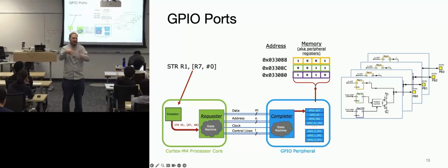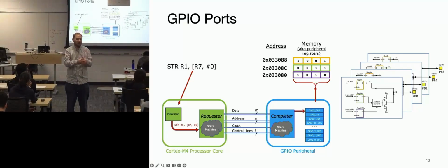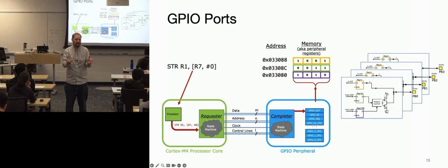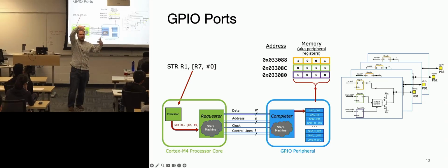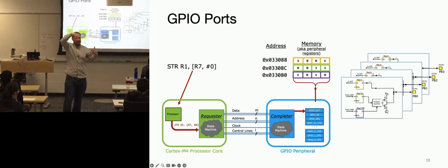So this is like the error condition that's built into the hardware. First, your compiler shouldn't let you. So QBID should say, hey, that's out of bounds. And if you do try to read from it, it's likely you're going to get nothing, because your row and column decoders, if you're trying to look at a memory address, will point to something that's invalid. So it'll probably give you back zeros or ones or nondeterministic values. In fact, a lot of times in your data sheet, it will say if you do this task, it's undefined, because they don't know what will happen.